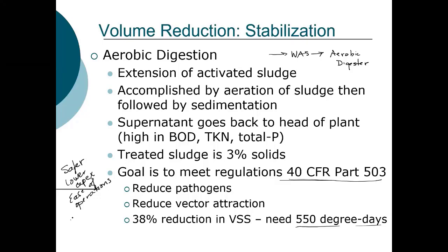The disadvantages are in turn compared to anaerobic digestion. It has a higher energy cost, and it's also very much temperature sensitive. And that's basically the same premise. You're converting BOD to COD, nitrogen to nitrate, phosphate forms from organic phosphate to inorganic.